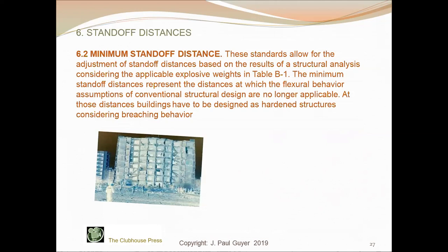The minimum standoff distances represent the distances at which the flexural behavior assumptions of conventional structural design are no longer applicable. At those distances, buildings have to be designed as hardened structures considering breaching behavior.